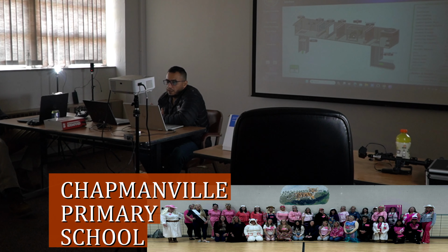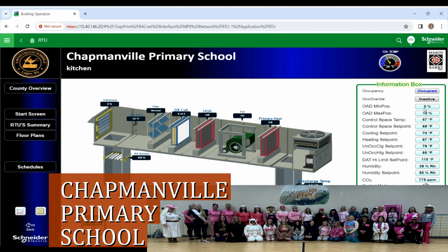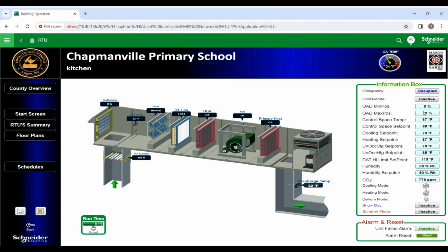Starting from the economizer, you don't have two actuators, actually, it's only one. Here's your outside air value, 0 right now, and the return damper is shown as 100%. This 100%, when I'm showing that, is just a calculated value. There's not an actuator running for the return by itself and the outside. They are sharing the same actuator.